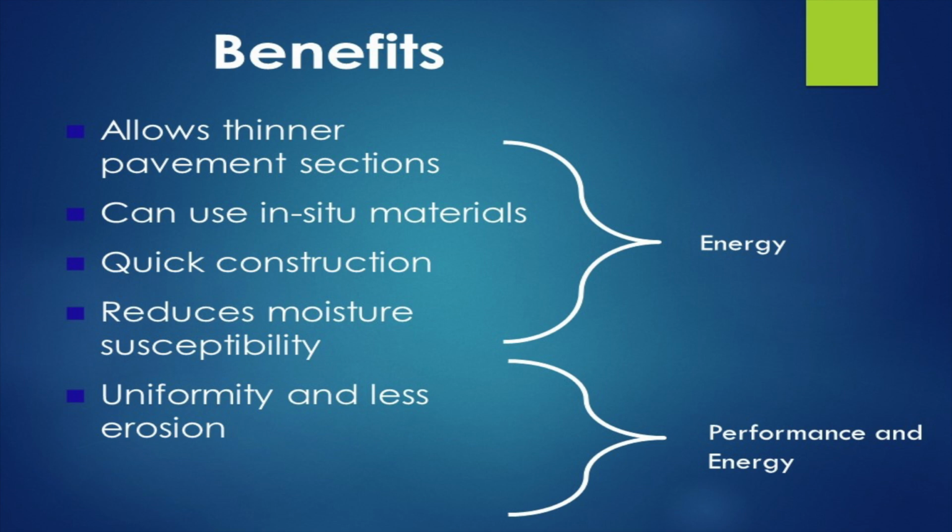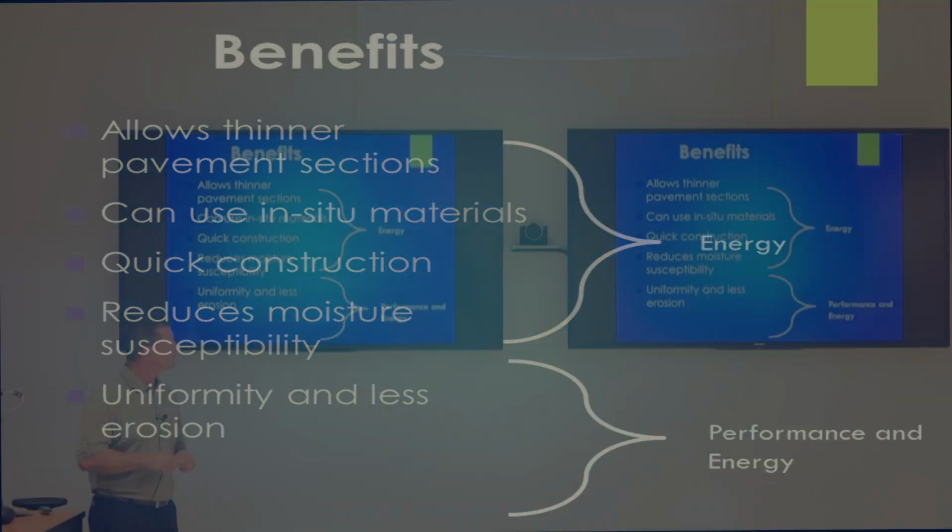One of the other things, the in situ materials, back to that. Whether you're up in Blacksburg and you're dealing with very fat clays, or whether you're down at the beach dealing with a little bit more sands and even dead sands, if you're familiar with those, and everything in between. This process blends all that material together, and that's why it's so critical to take some soil borings and take some samples so you can get a mix design, so you can find out what's out there, so you know what material to apply, what additive to apply, and how much.